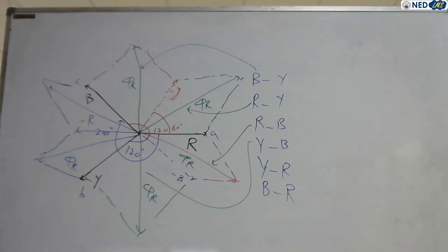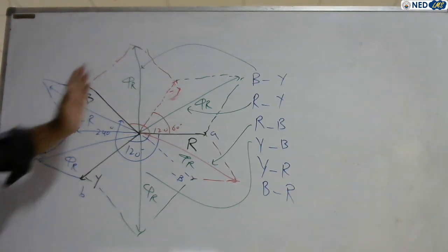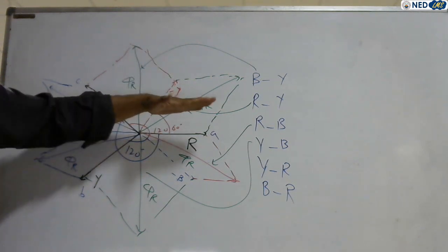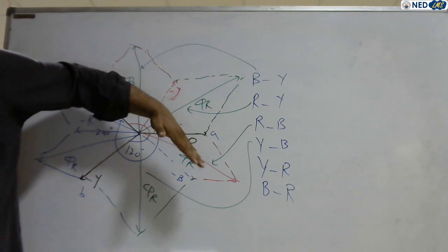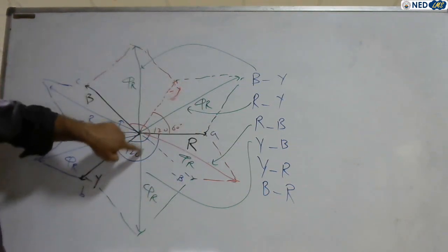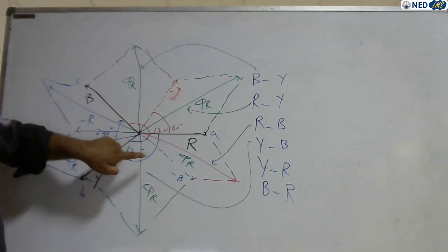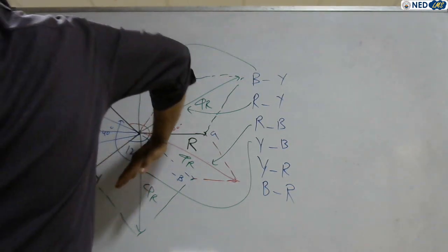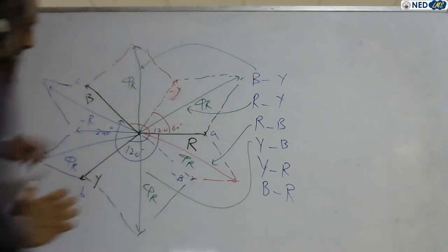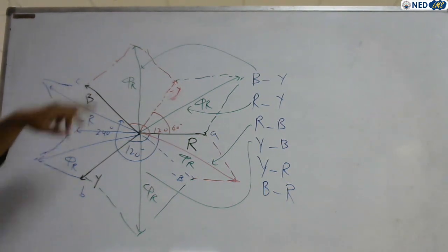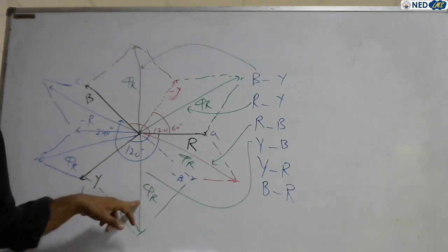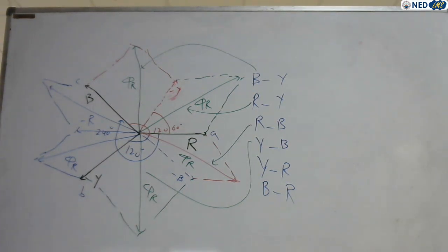Now in this diagram it is very clear. The resultant vector was first in this direction, then the resultant vector comes over here, then it rotates and comes over here. From this to this is 180 degrees. The resultant magnetic field vector is rotating, and it comes to this point. In this way the resultant vector rotates. So this is the rotating magnetic field, right?